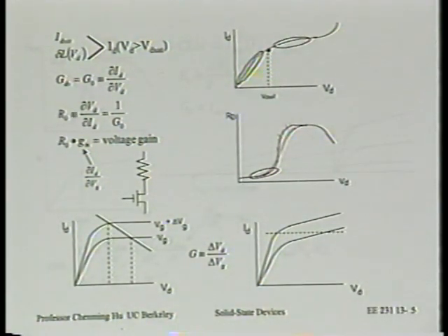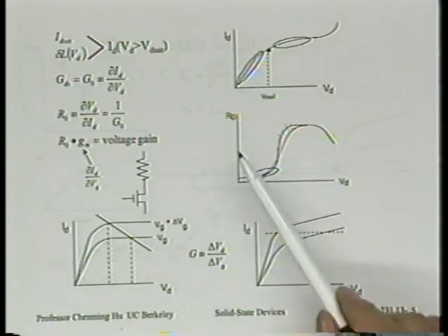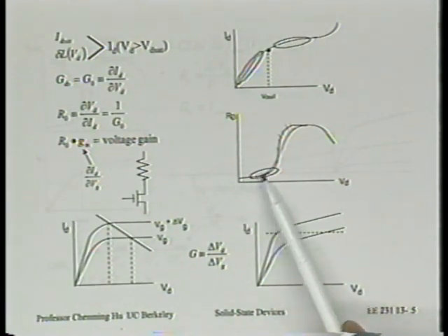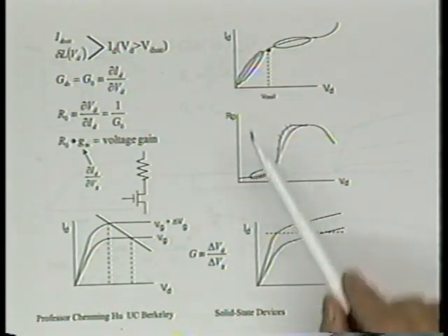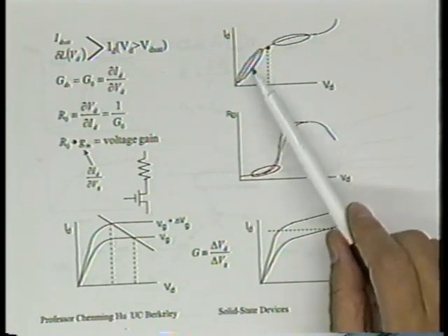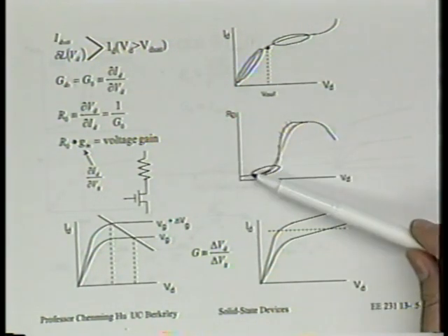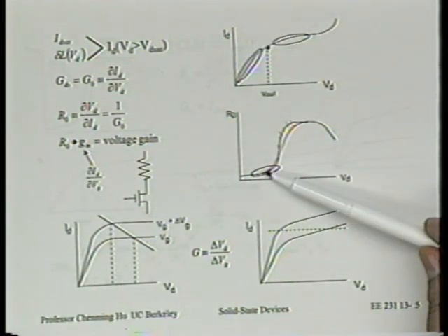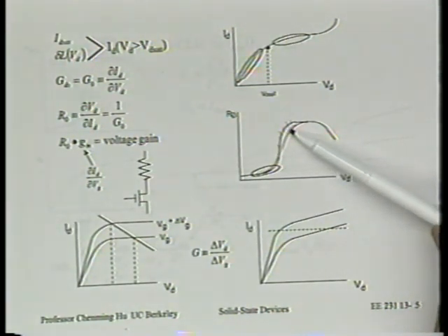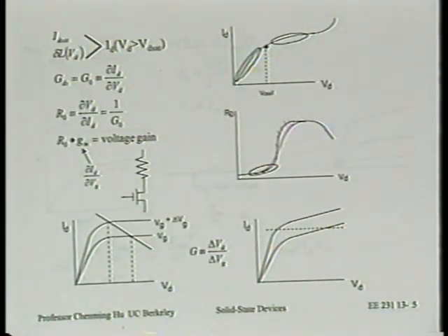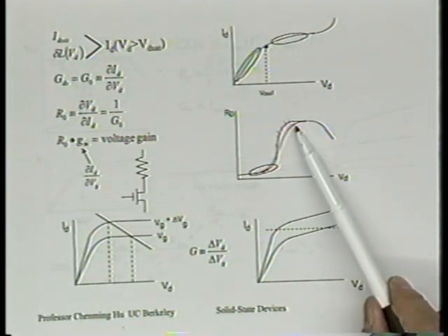Okay. Typically, what you see is that first, this output resistance is fairly small, which means the gradient is large, which is here. Slope is large, linear region. We're not worried about it. And then this output resistance rises fairly rapidly. That's when we transition from the linear region to the saturation region. Then we actually kind of peak over a region that is fairly flat.